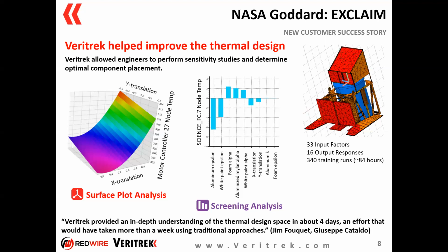The runtime to perform a single Thermal Desktop run of theirs was on the order of 15 to 20 minutes. And typically, the more input factors that you want to include in your reduced order model, the more training data runs you're going to need in order to produce an accurate ROM. So that can be a limiting factor in some cases,